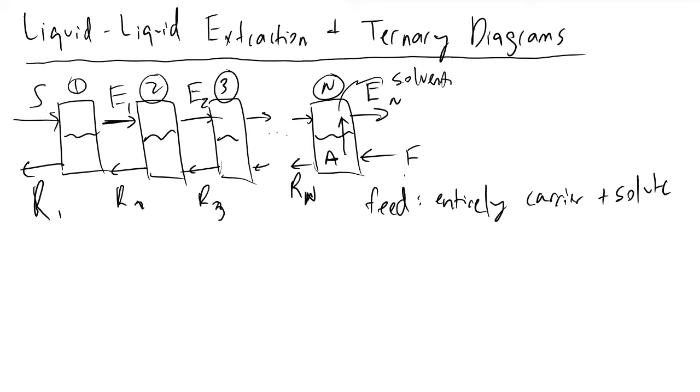The reason we generally operate liquid-liquid extractors in a countercurrent fashion instead of a co-current fashion is because this maximizes the concentration difference at every single stage in our unit.